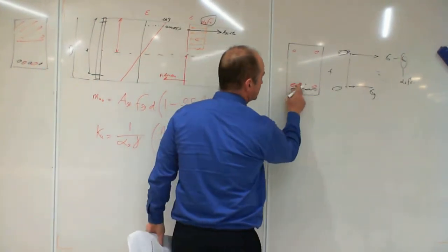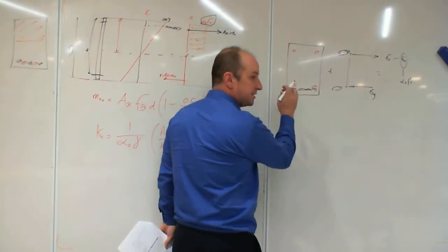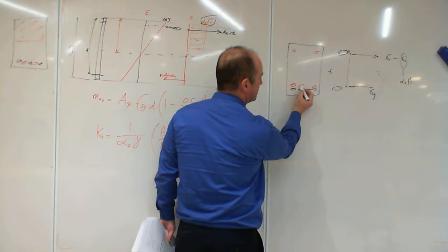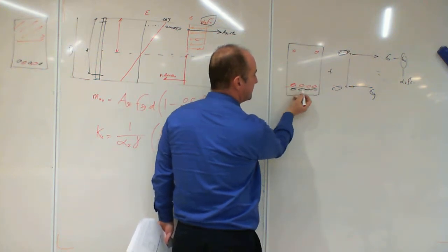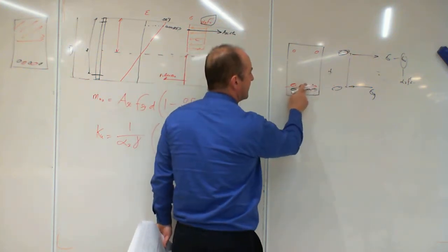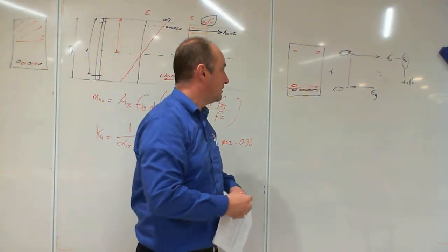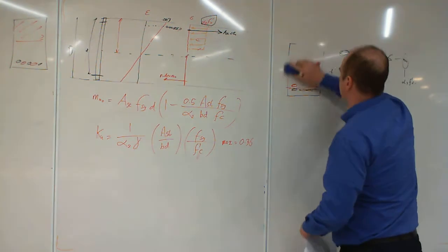Normally, if it was just the black, you take it down to the center point of the bars. If it's the black and the red, you have to find the centroid of that. If it was, say, 4 bars in each, then it's the midpoint. That's easy. If those two aren't there, then it drops a little bit closer to that. But you've got to find that. All right, let's have a crack at the problem then.